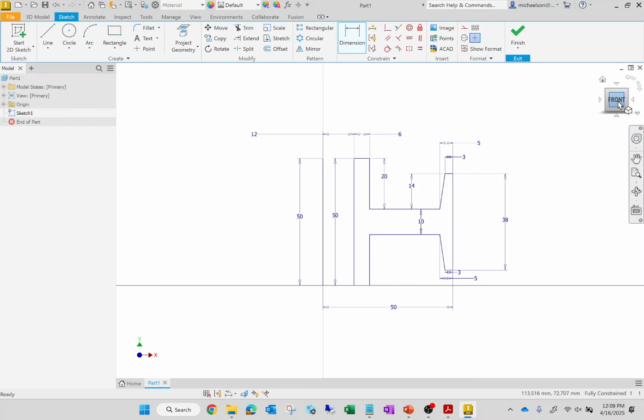Okay. So I'll give everybody a sec on this. Again, as you're dimensioning this, if your sketch starts to behave wonky, you can always just undo that dimension and then place another one. Okay. Again, I wish I could give you better, more specific guidance, but it just depends on how you draw the initial sketch. If you accept certain snaps that Inventor is trying to place, Inventor is going to place different constraints on your sketch than maybe somebody sitting next to you. So.